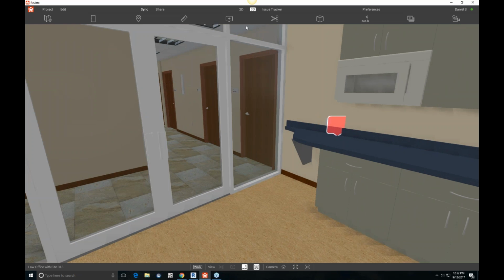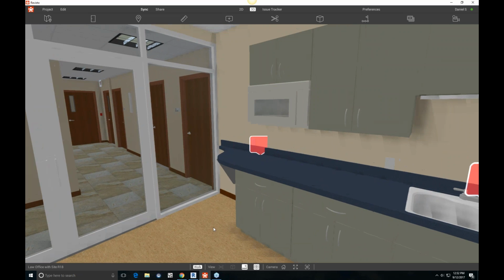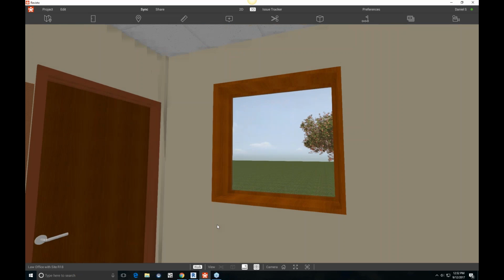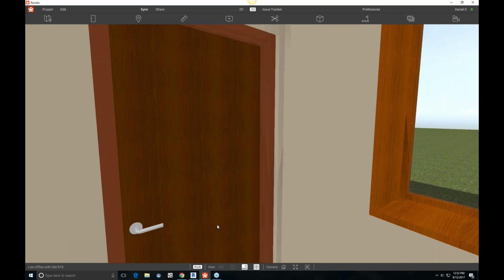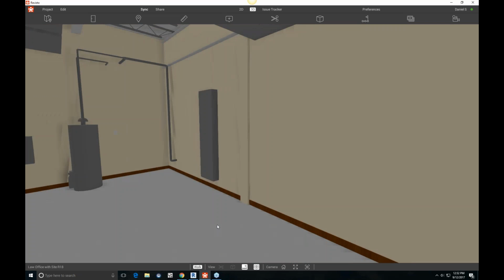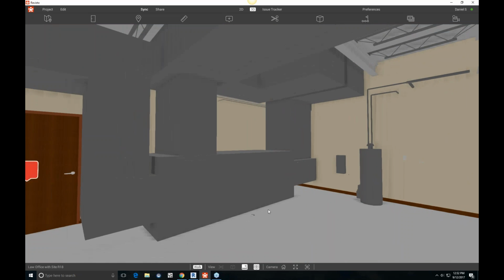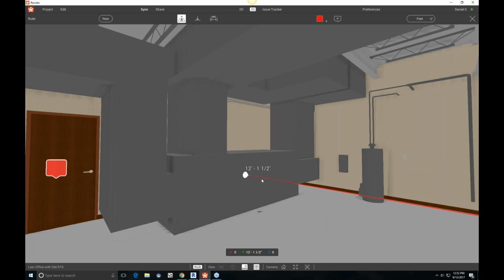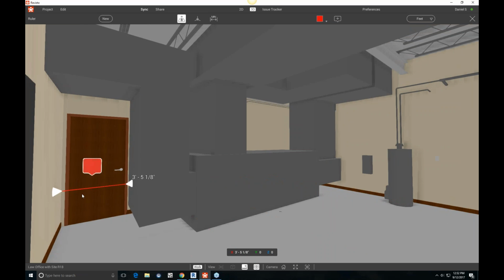A couple other really handy things with the software is the ability to measure. I'm going to turn walk mode on, and when walk mode is turned on, you'll automatically go upstairs, but you can't go through walls, and you can go through glass and doors. So here's a mechanical room, and maybe the client's starting to wonder about some certain dimensions in here. I can click on the dimension tool and see the clear space here, but there's also an issue over here. Maybe it's kind of tight,